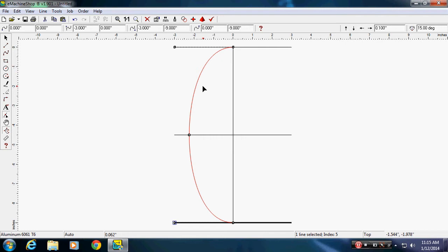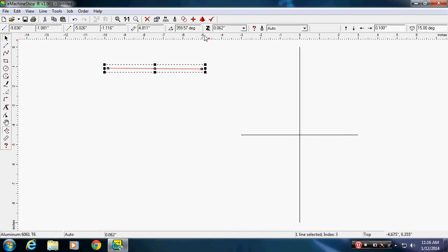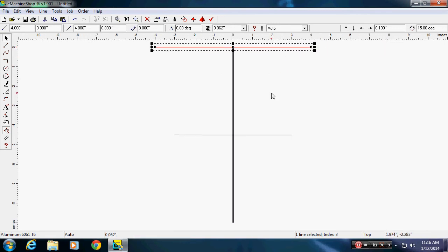Let's go ahead and delete everything off of here. Delete the top and bottom lines. We have 6 inches, and I'm not going to show the calculator, but I have 6 times 1.3333 equals, I'll go 4 spaces, and that comes up with 7.9999. So it's 8 inches. So I'll draw a line 8 inches, 2 of them. And of course I went back to my old habit of not holding the control key. I'll hit Control D.